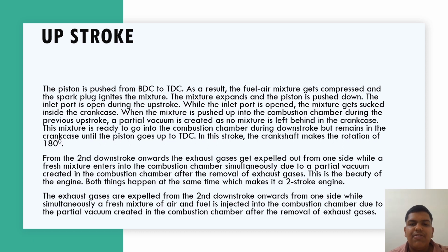As a result, the fuel-air mixture gets compressed and the spark plug ignites the mixture. The mixture expands and the piston is pushed down. The inlet port is opened during the upstroke. While the inlet port is open, the mixture gets sucked inside the crankcase.